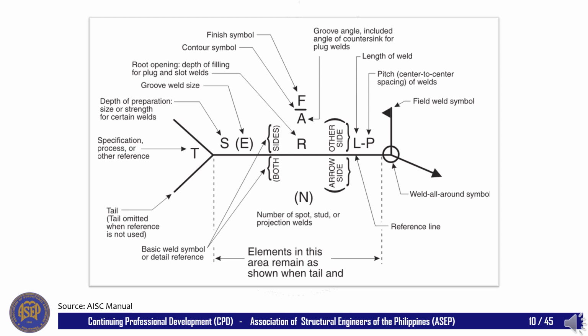Here's a standard format for weld callouts. It includes, at a minimum, a reference line and an arrow. A tail may be added opposite to the arrow end as an option to indicate any specification, processes, or notes. The arrow should point to the joint. The weld symbol designates the type of the weld. It could be fillet weld, PJP, or a CJP weld.